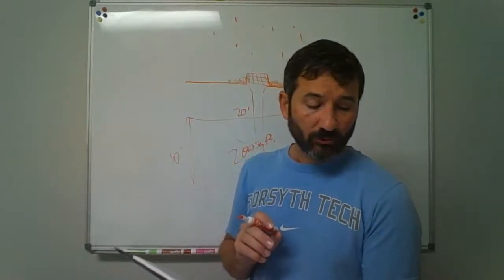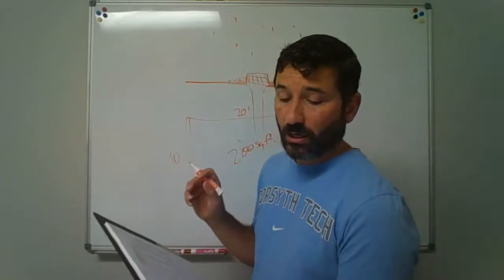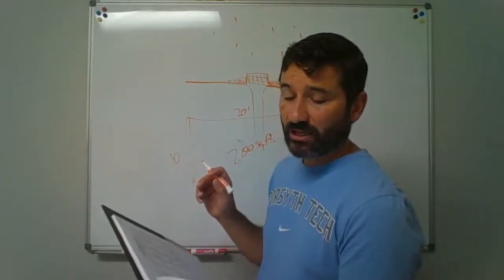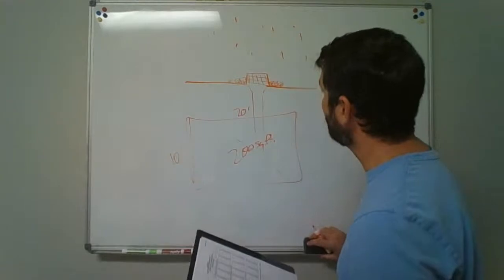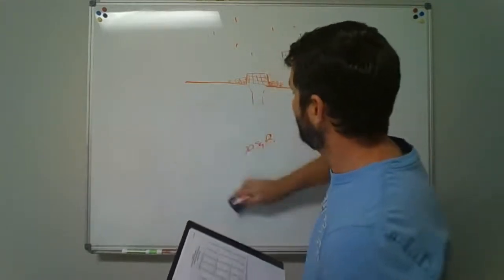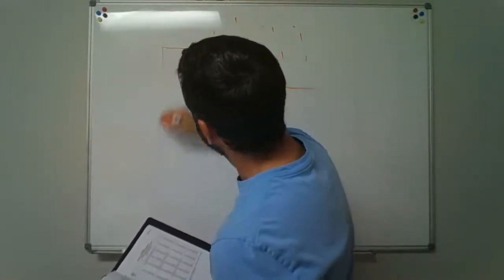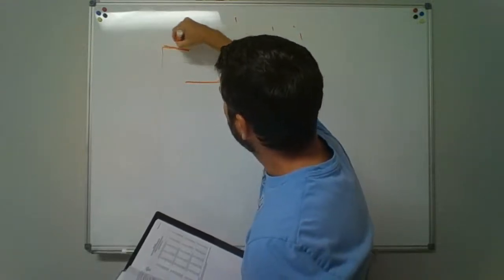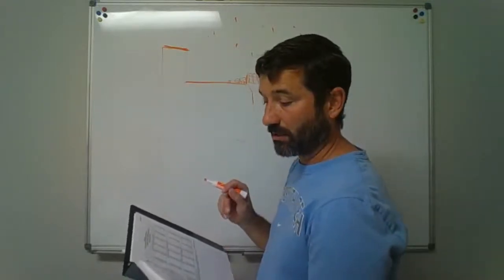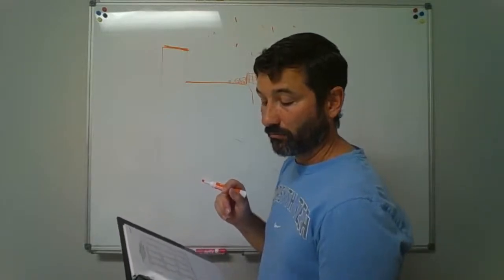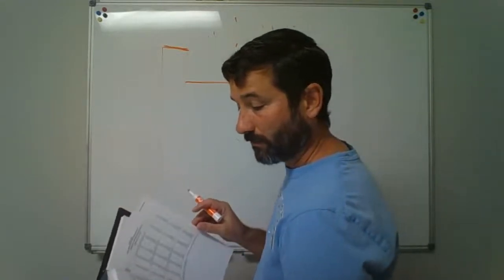Let's see. Vertical walls, inside roof drains and storm drainage piping: one half of the area of the vertical wall that diverts rainwater to the roof shall be added to the projected area for inclusion in calculating the required size of vertical conductors. So basically, it's saying if you've got a flat roof and a wall that's built up beside it, and you've got this area that's tapered to where water is going to run, the wall that's built up, this area on top, is calculated into the roof area.